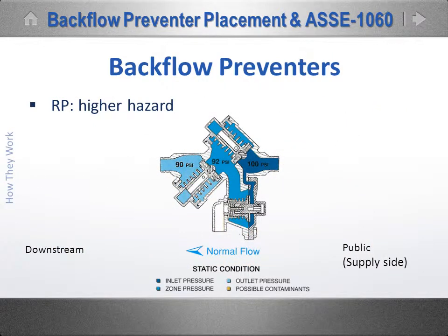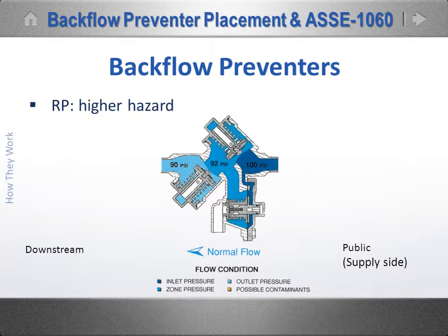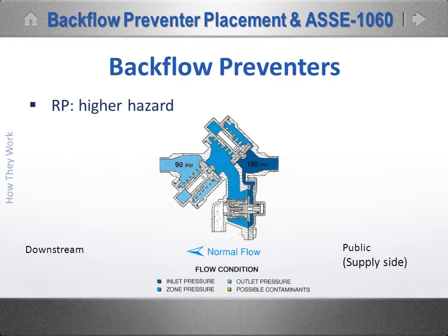The reduced pressure zone assembly consists of two independently operating check valves, just like the double check, plus a hydraulically operated differential relief valve located below the first check valve. This hydraulic valve and its placement make the RPZ virtually fail-safe. It's really quite elegant, but it does come at a cost to the area around the device. When a back siphon occurs, both check valves close. At that moment, the relief valve will open every time and evacuate the water between the valves.